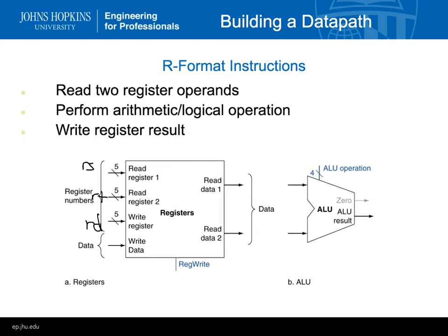They're going to be values, and this register file is going to read it. It's going to read those bits that represent the RS, then go get that data. Whatever this number is, it's going to go to that address in the register file, read the data, and send it out. Same for RT or RD. There's several options for the second data value, but whichever one it is, that data is going to come out here.